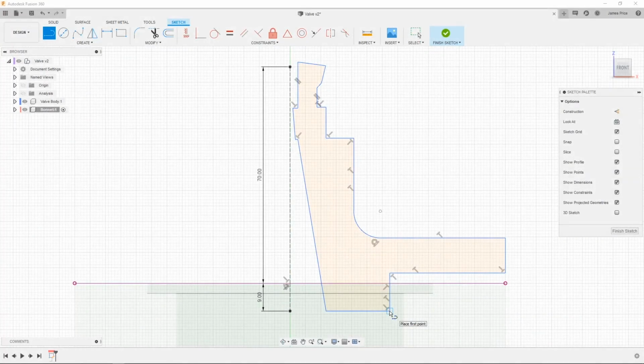Regarding constraints, you will also find automatic constraints placed when creating certain sketch features in a certain way, as with SolidWorks. For instance, in this simple sketch here, you can see a perpendicular, parallel, and tangential constraint automatically applied, as indicated by the glyphs. If this constraint is not wanted, you can simply delete the glyph to remove.